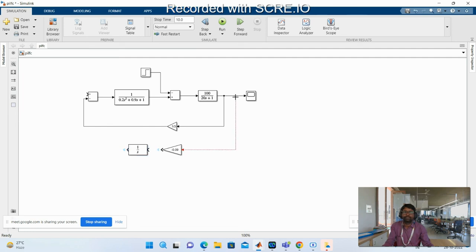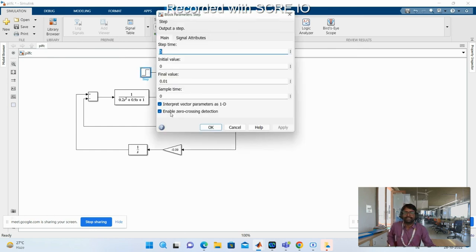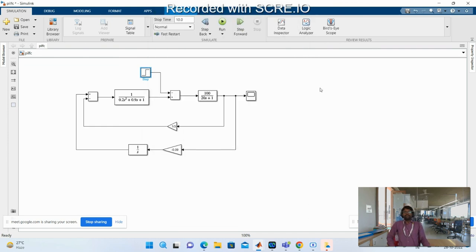Scope. And this one goes to the adder. And this one goes to the adder, this is the delta PC. So you are getting the command signal to the speed changer from the PI controller, which takes the frequency deviation and sends the signal, and so this changes, right? So what is your expectation? So this is your PI controlled load frequency control system.